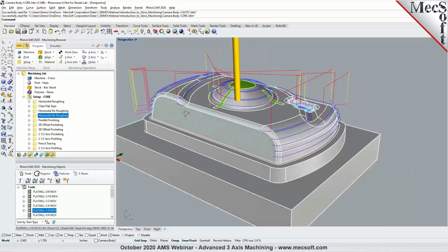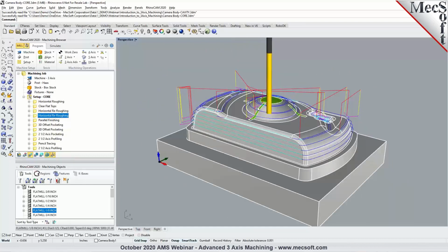Well, there was a question about pencil tracing toolpaths, smoothing, and also the same thing in valley remachining. I can talk a little bit, and then you can add your thoughts as well. As I mentioned, the pencil tracing and valley remachining methods use bitangent contacts. So by nature, we are detecting bitangent contacts, and in some cases, these are more than 2 contacts in some situations, except if you're cutting a fillet, for instance, with a cutter of the same radius. It is really a very difficult mathematical problem for us, because you're going to have very many places where the cutter is contacting the fillet.